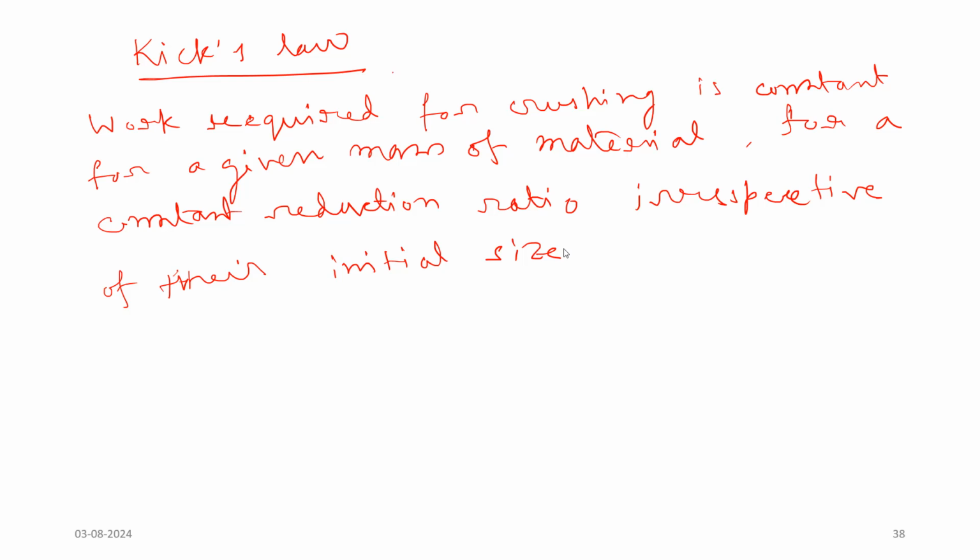So irrespective of their initial size, the work required for crushing is constant. It will be defined as work required, and this is constant, depending on the feed particle size to product particle size ratio. This is the Kick's law.